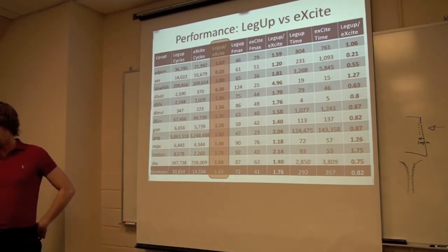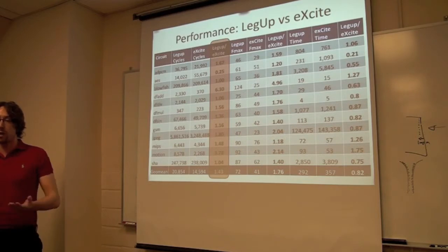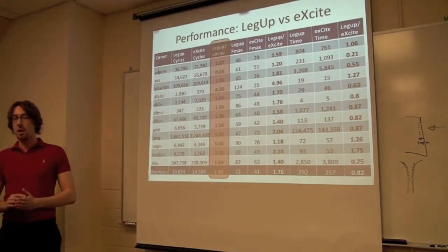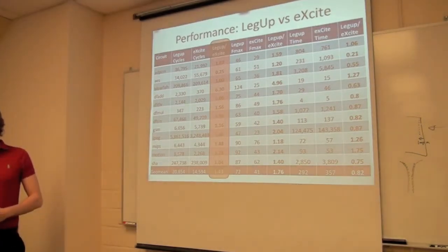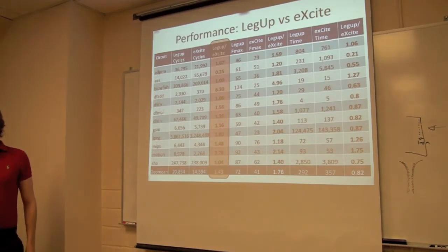In terms of the limit of what you want to do, it's hard to answer that. If you scaled up to a Stratix 4, you could start putting some pretty big programs in. But you couldn't put a 1,000,000 line C program through this flow, probably, because to support all that C syntax you'd have recursive algorithms and so on. So JPEG wouldn't fit on the Cyclone 2, and if you wanted to do MPEG, with actual video, then you definitely have to go to a Stratix.